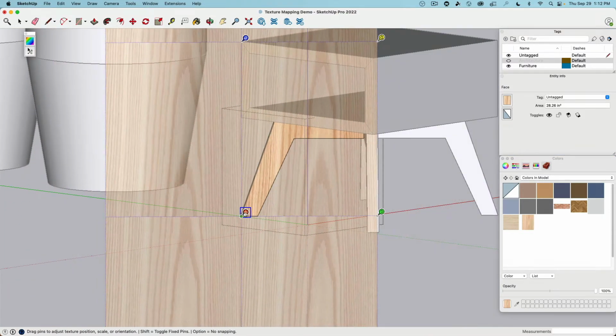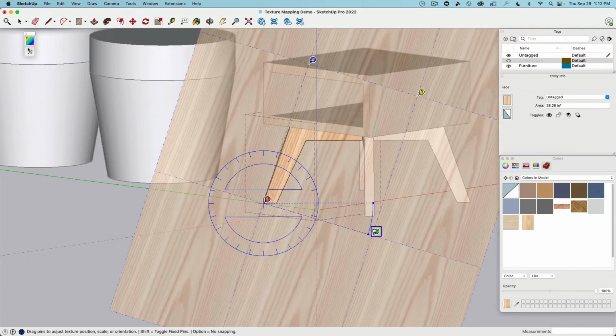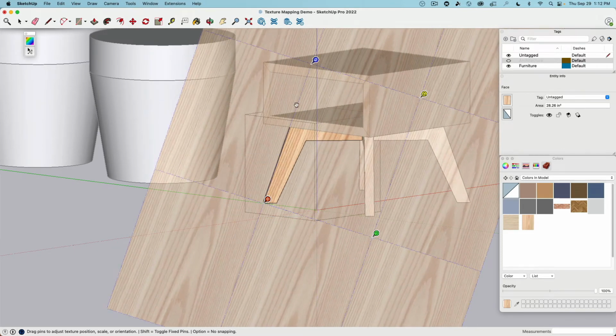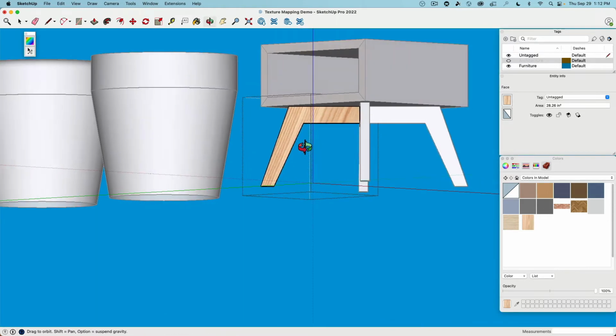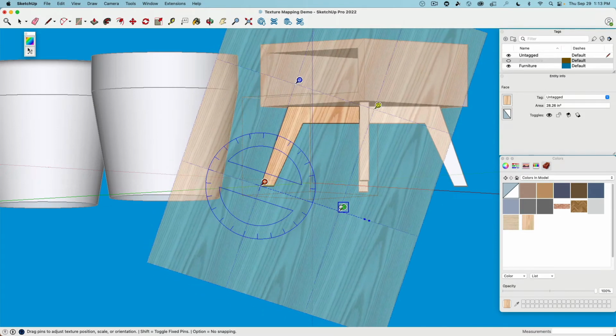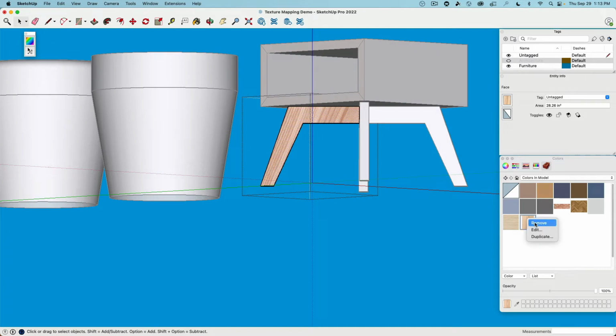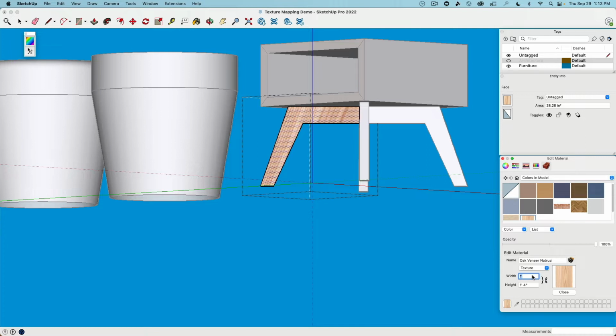So now I bring this texture to this corner, and we can see the veneer, the grain going up and down, and I'm going to rotate it, and I pay attention to this dotted line so that it actually lines up with this part of the furniture. Yeah, can also scale this down a little bit. Yeah, so maybe edit. Oh, look at this. It actually ignored this 8 inches. There. Hit enter. Okay.